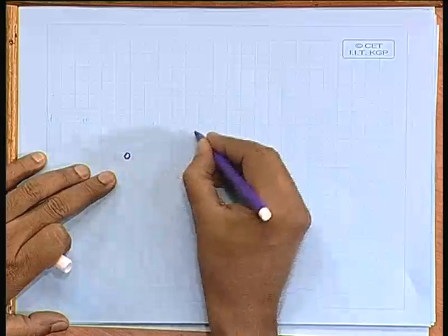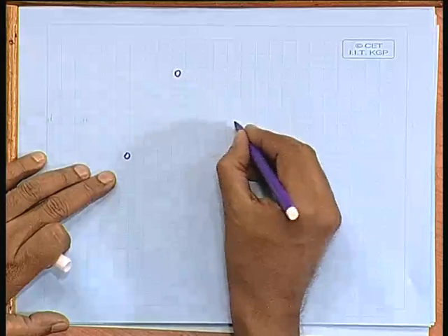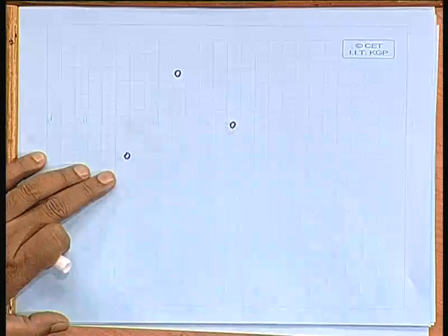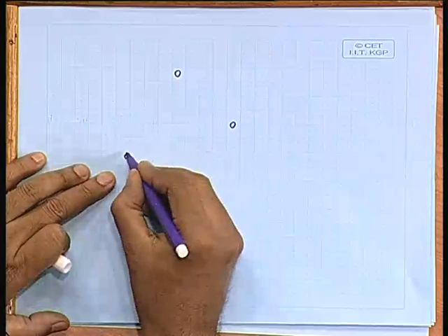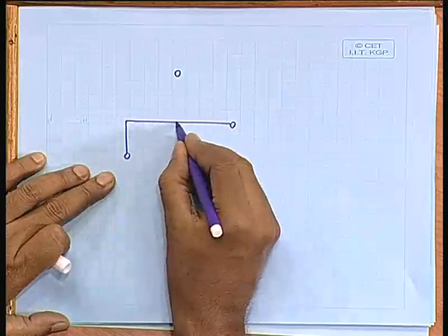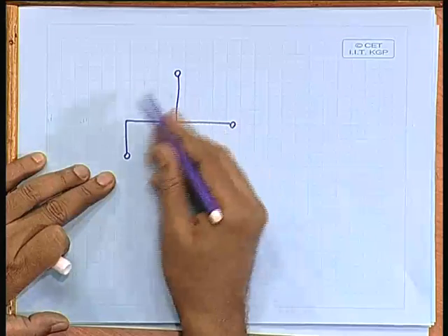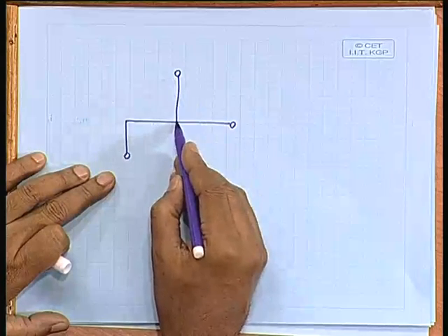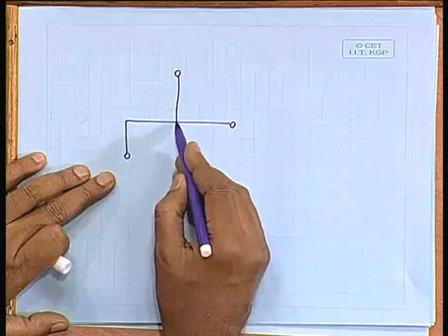But this is very obvious, that branching is allowed only at pin locations, because the pin locations are actually the nodes. I am mentioning this because you may have a situation like this, for instance, where you want to connect say a pin here, a pin here and a pin here. Now, in this case the optimal interconnection path will be like this. In terms of a graph, this edge is branching out from the middle. This is not a vertex. That is why I explicitly mentioned that point.